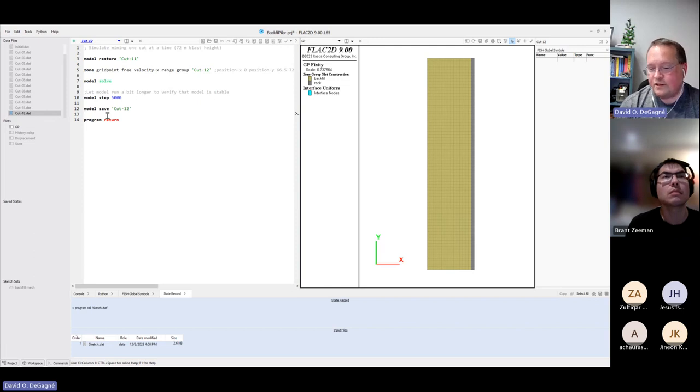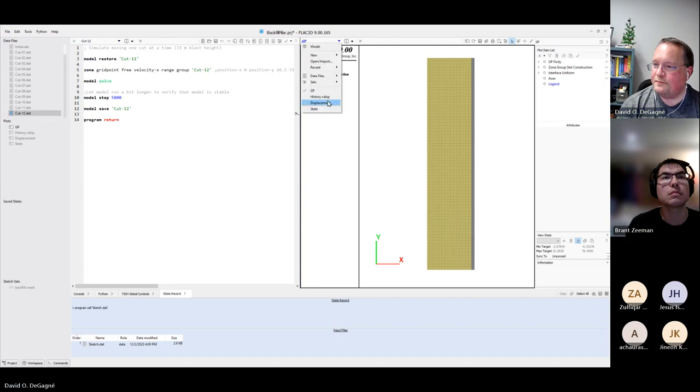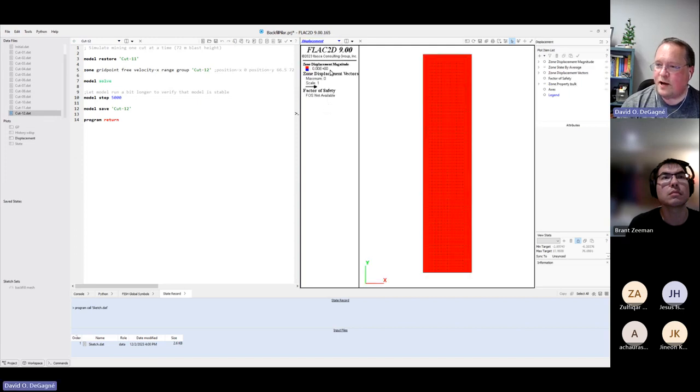You'll see that it'll do a whole bunch of automatic modeling, and in the end, you'll see on, I believe it's the displacement plot, there'll be a factor of safety value here. We're not running that analysis, so that value isn't available here for what we've done. But when you do run a factor of safety, you'll see a value there, 0.8, 1.2, whatever, 3.7. And again, the goal is to be greater than or equal to 1.25.